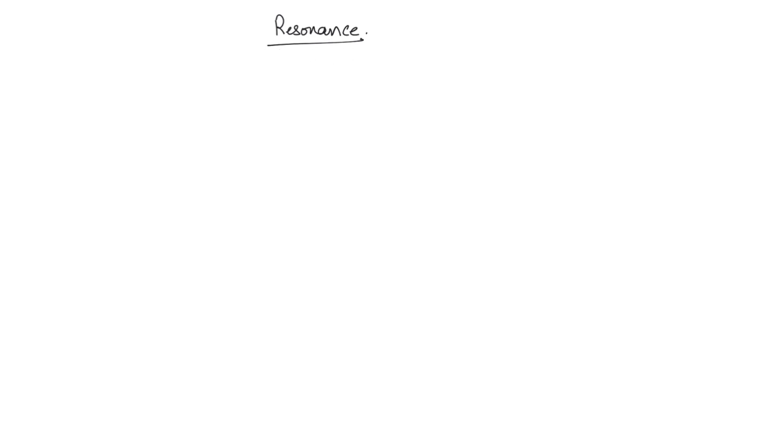Okay, so you can listen carefully here. What is the definition? Basic condition for resonance is what? The capacitive reactance is equal to the inductive reactance. Right? So this means that whatever energy the capacitor and inductor absorb for a half cycle, they deliver for the other half.